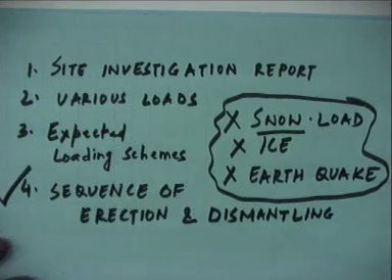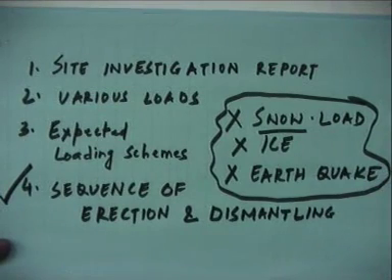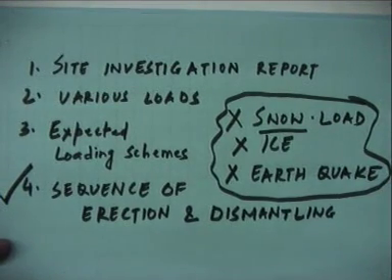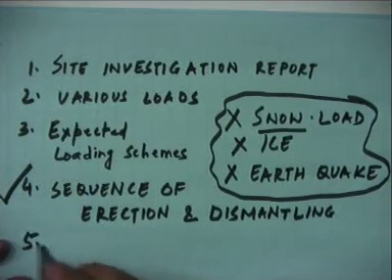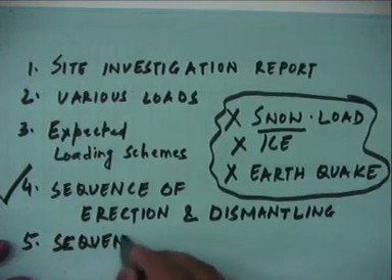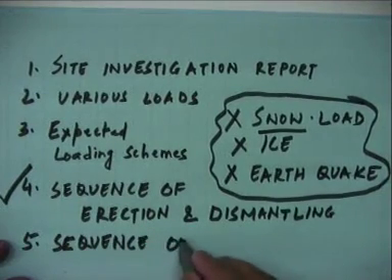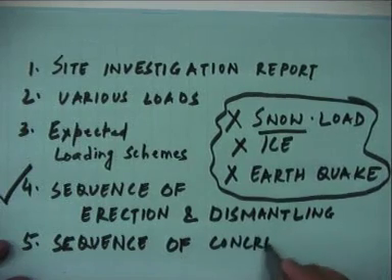So the knowledge of this is needed, because if you are trying to follow a given sequence, the loads may act differently. The moment you change these erection and dismantling patterns, your loads are going to be different. Similarly, the sequence of concreting, in what sequence you are going to cast your concrete element, that also is of immense value to you.